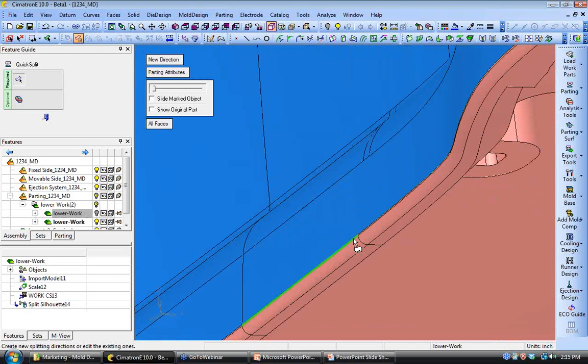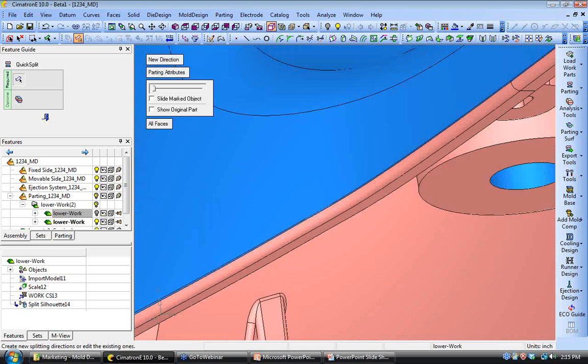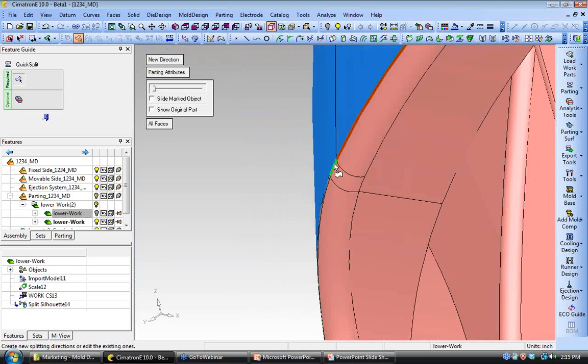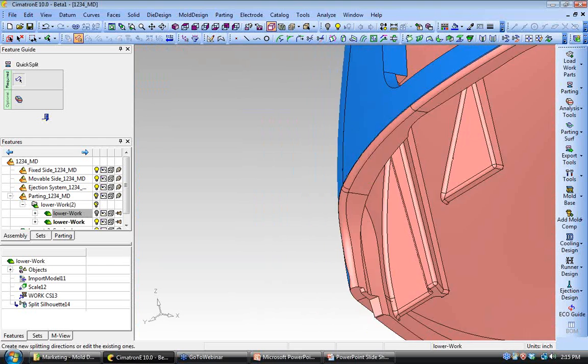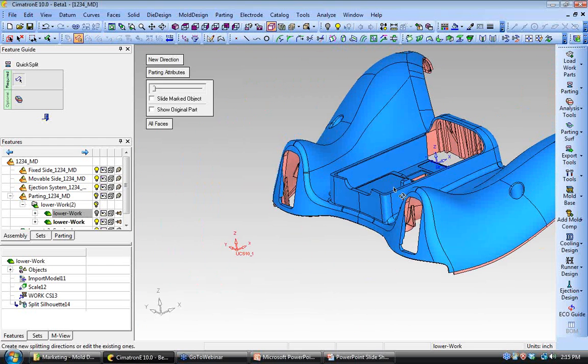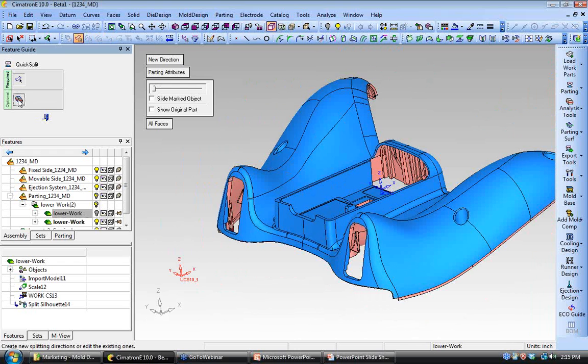One other note on the split silhouette, which is a very nice command. With the split silhouette, you can also enter in a value for 7 degrees, so it will split from the horizontal up or down 7 degrees. You know, if you have to have grain or texture in the mold, you can automatically get that line, instead of at the silhouette, up 7 degrees.